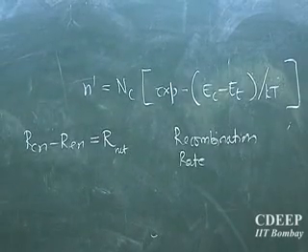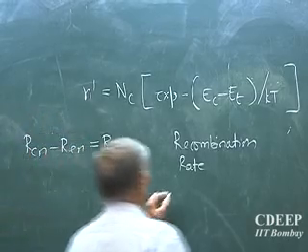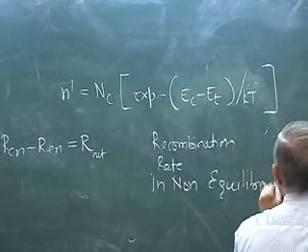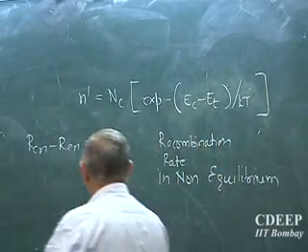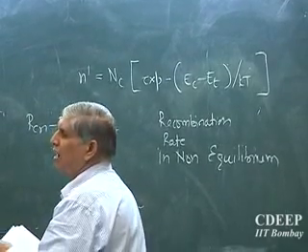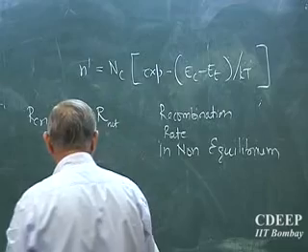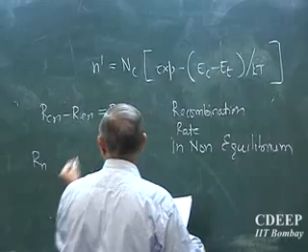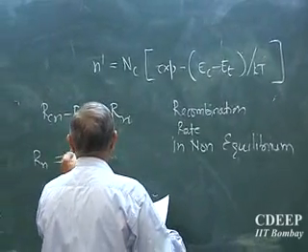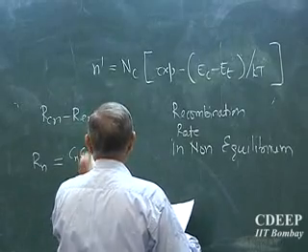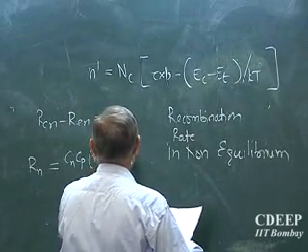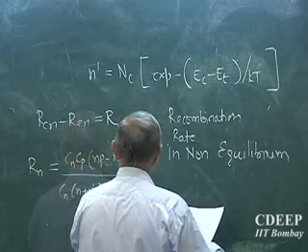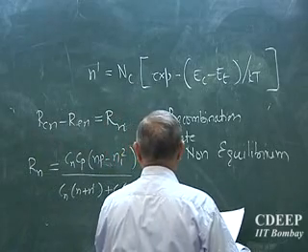So in the non-equilibrium case, if I solve those expressions once again, you solve it yourself. This is given in Neamen's book or Sze's book. I am just reproducing Rn, which I call Rn net, which for electrons is CnCp (Np minus Ni square). Just substitute all that again and solve this. P dash N dash is similarly written as I wrote here.